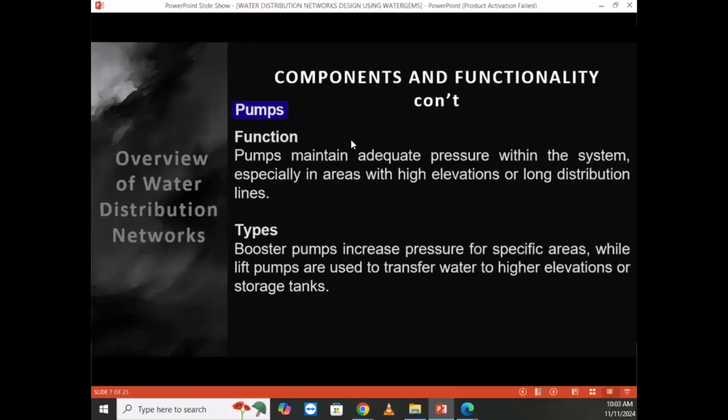So you may be starting from the source and you pump. Add your pump here to pump your water. You may put it in the system, but it is not encouraged. Put a pump in the system so it will pump to the end users, unless it's the last scenario that you may need. But most of the time we put the tank to lift water to another reservoir. By locating your reservoir, you are now required to see if the place you are locating your reservoir is helping to have the minimum residual pressure that is required at each end point.